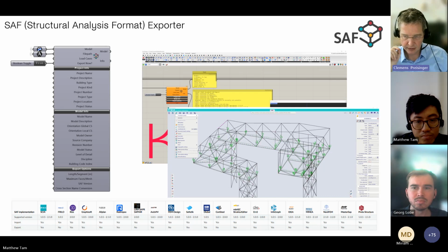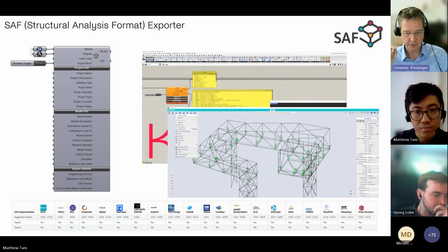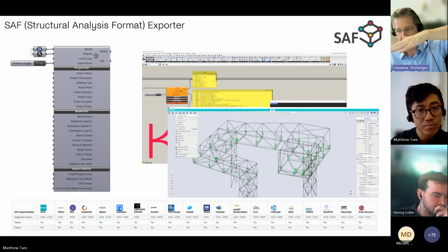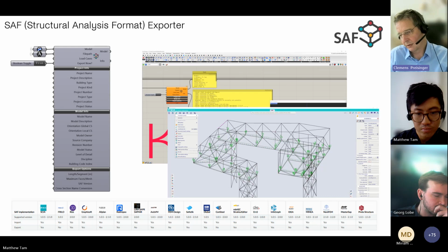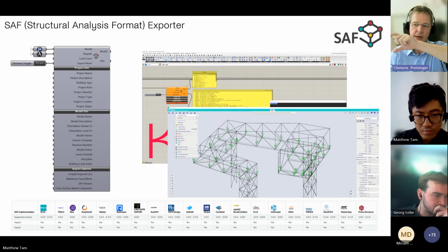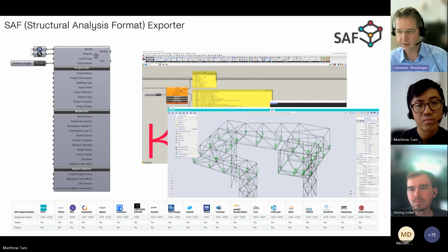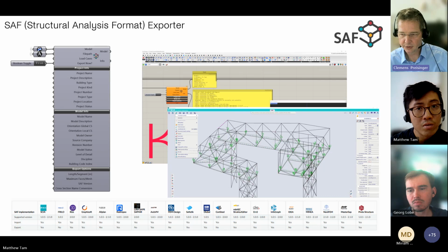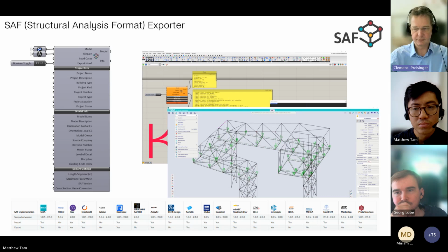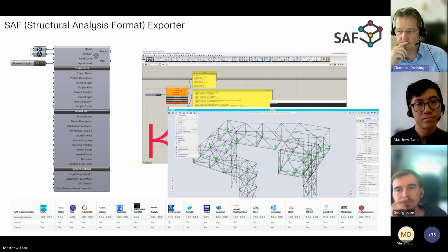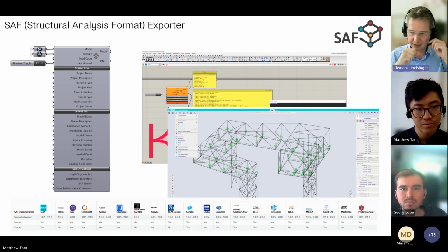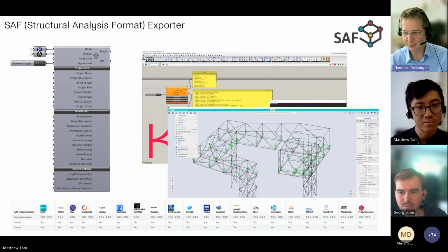This is also something which will likely change, because now it's very easily possible to place arbitrary line loads on beams. So this then will also make it feasible to have not only a uniform load distribution from the mesh load on the beams, but a more precise one. I hope this answered the question. And by the way, this is also something which is a little bit of a problem in SAF, because SAF differentiates between these load surfaces for shells and for beams, which is not the case in Karamba. But there will be a corresponding paragraph in the manual.